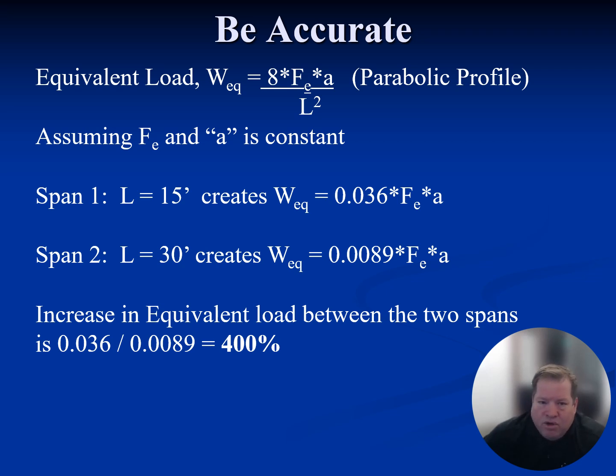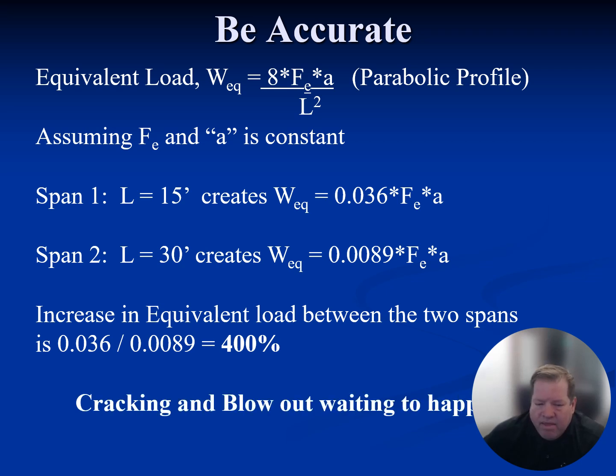That is going to crack the slab. That is going to create cambers. That is possibly going to create blowouts. That is not the right solution. Even though the strength, if you're to cut a free body diagram and you have all those tendons at the bottom, from a strength perspective, it's great. You have extra strength. The problem is when you're lifting that thing up every day of its life, you can't be 400% higher than the weight of that slab. That's where cracking happens. That's where blowouts happen.